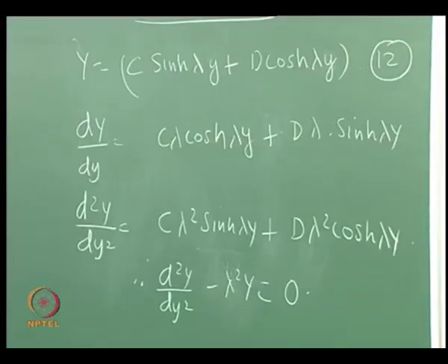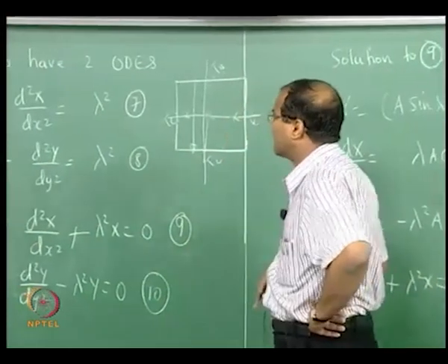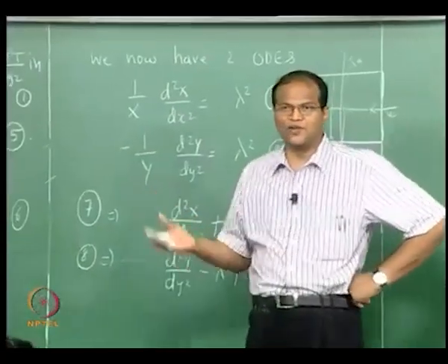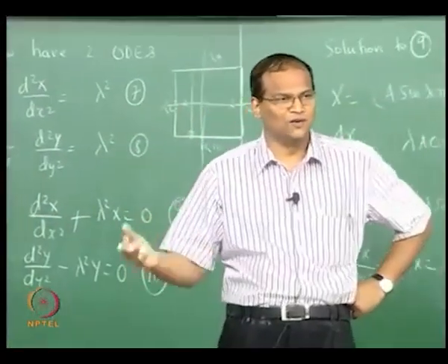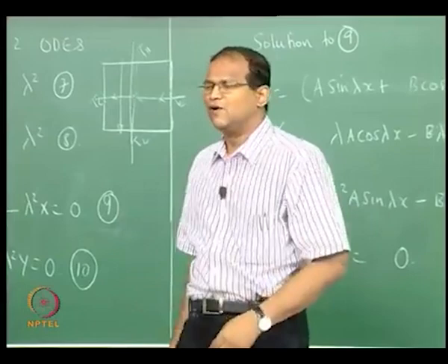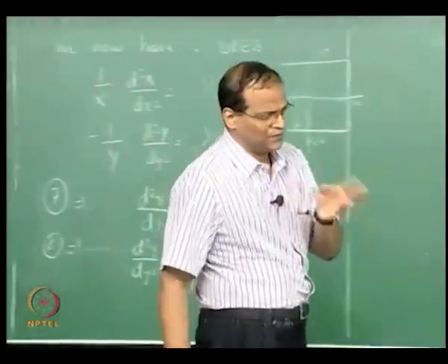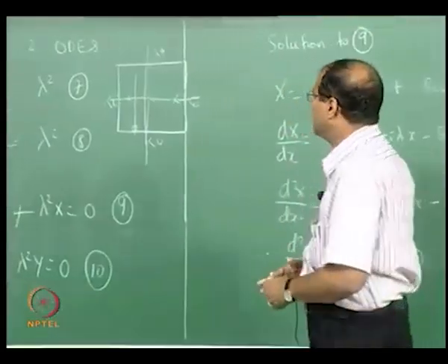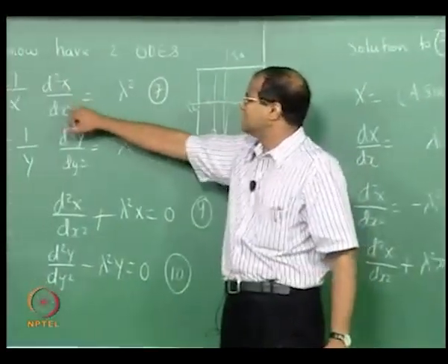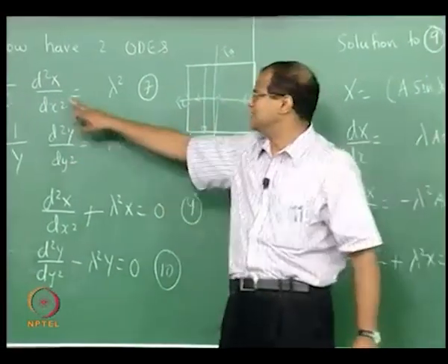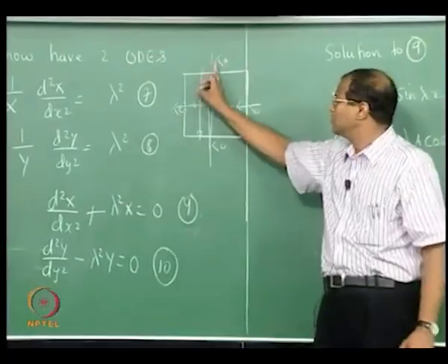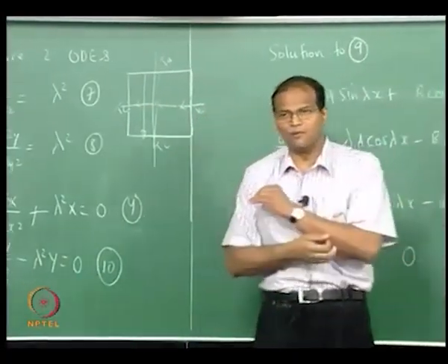So, we are on firm wicket now, we have got the general solution to the problem. Obviously, it is an elliptic equation, because from the method of characteristics you can prove whether b squared minus 4ac is less than, greater than or equal to 0. You can figure out whether a partial differential equation is elliptic, parabolic or hyperbolic. Once you have established it is elliptic, because it is second order in x and second order in y, it supports 2 boundary conditions in x and 2 boundary conditions in y. So you require 4 boundary conditions for closing the problem mathematically.